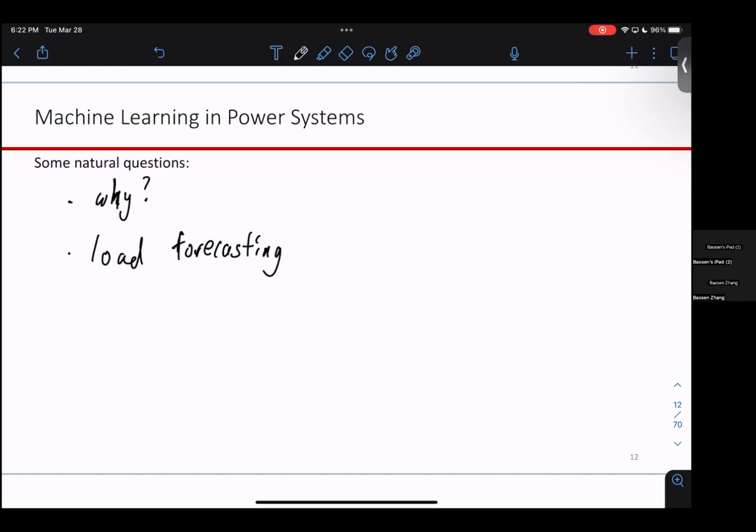Okay, so you have generators, things like nuclear and coal, that take a very long time to ramp up. So you need to tell these generators tens of hours ahead of time what their generation level should be. For example, right now we're determining what this hydro plant should produce for tomorrow at 6 p.m. Obviously you need to forecast the load. We don't know what the load is for tomorrow. So load forecasting is the fundamental operation we do in power systems.